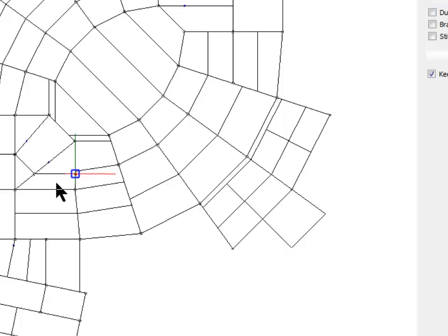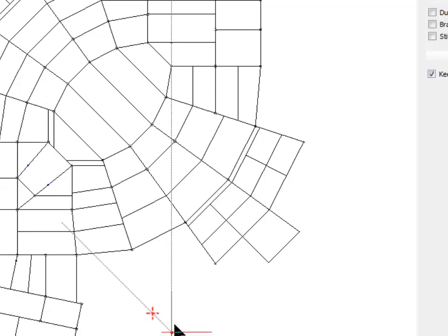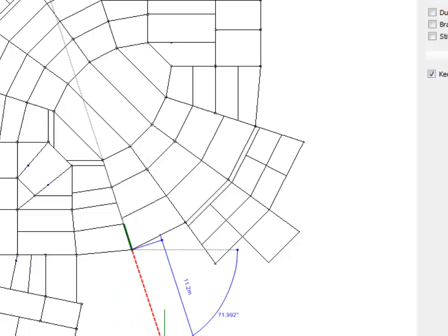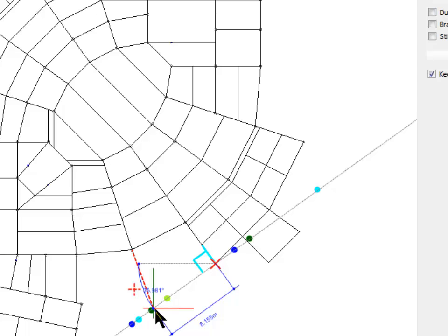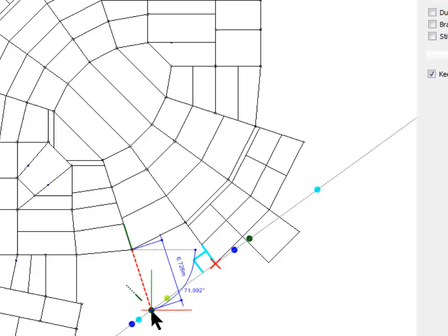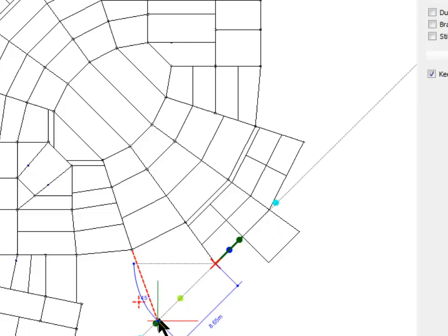It's just so beautiful. So I can come along, and if I wanted to say take an extension along here, that's just coming straight for me. And if I say I want to also take it off here, I can get that intersection point of those, and there I go. I'm now intersecting at that point, and it does it for me.